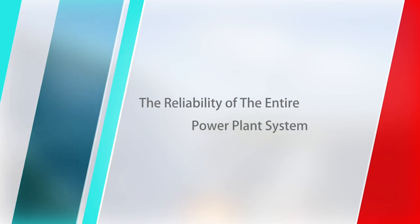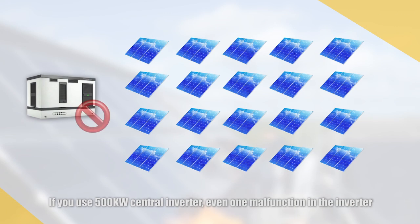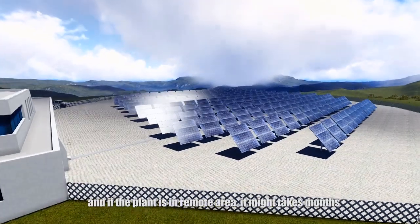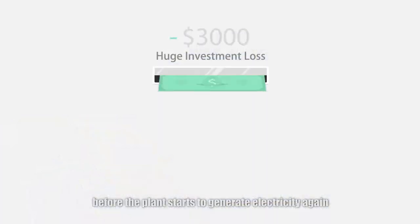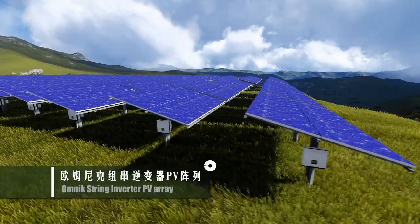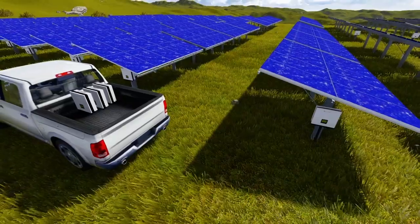The reliability of the total power plant. If you use a 500 kilowatt central inverter, even one malfunction in the inverter may lead to panels of 5,000 square meters stopping work. And if the plant is in a remote area, it might take months before the plant starts to generate electricity again. With 20 kilowatt inverters, the same kind of risk is reduced to a minimum.